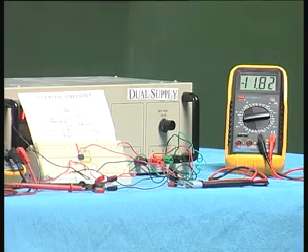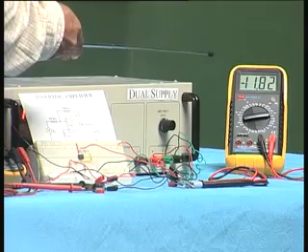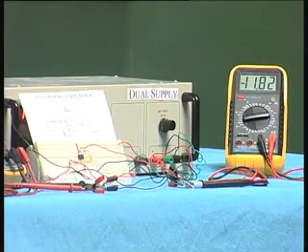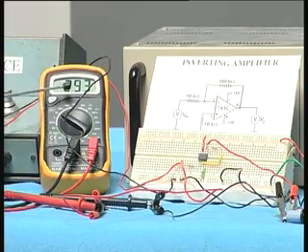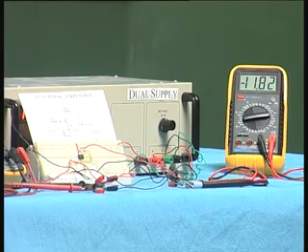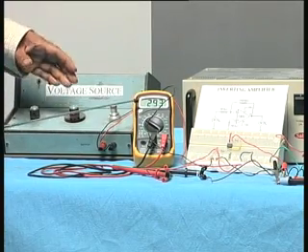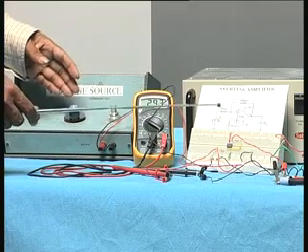I have put here 2, it is now 1.95 volts and the output is 11.82 only. Now if I go to 3 volts, here it shows 2.93, nearly 3 volts, but the output still remains at minus 11 volts. Why? We say the op amp is now in saturation, because the input voltage is very large multiplied by the gain factor.